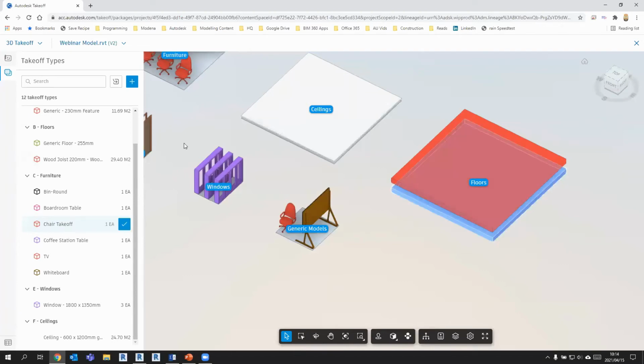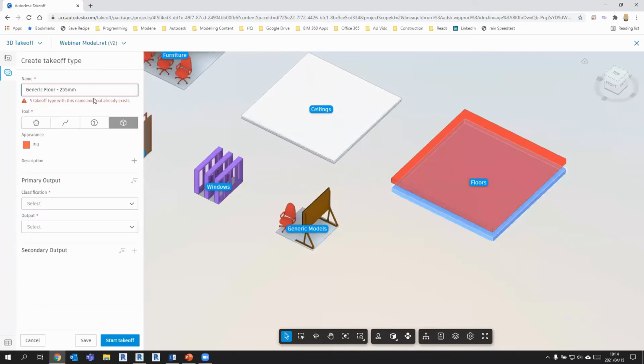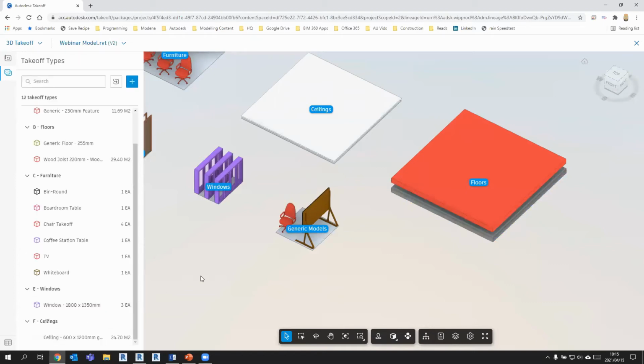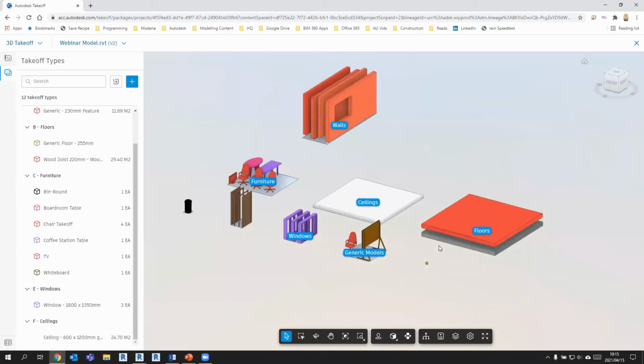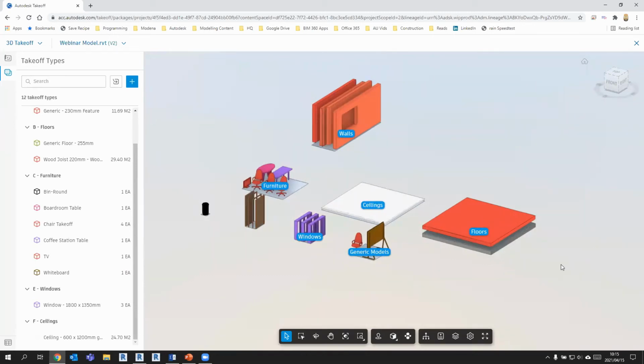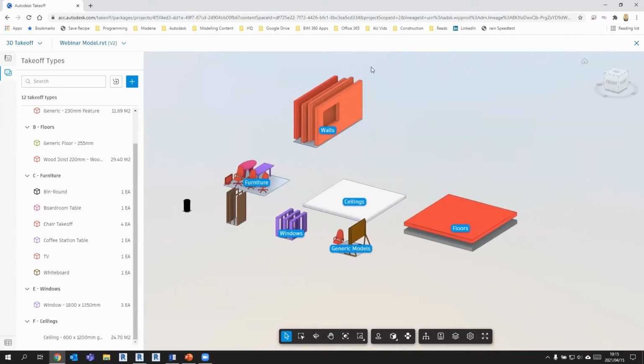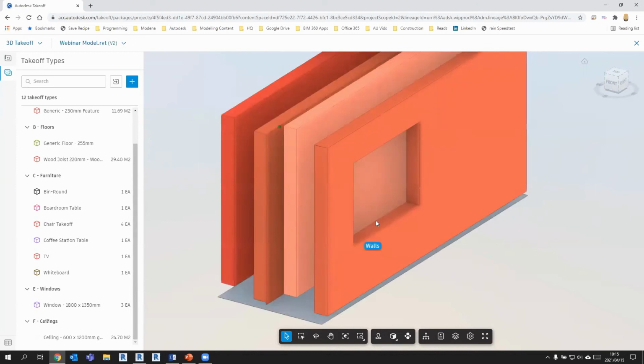What's typically nice, even if you want to create a takeoff, it'll give you a warning that this has already been attached to a takeoff. So you can avoid doing double takeoffs from the system. Okay. So yeah, that's taking BIM takeoffs. Now you can imagine bigger project files, you can have columns, everything will be grouped into their specific areas, and you can track what you've been taking off and what's not. Especially if you're doing packages and one package only contains walls, you know you only have to focus on this element.